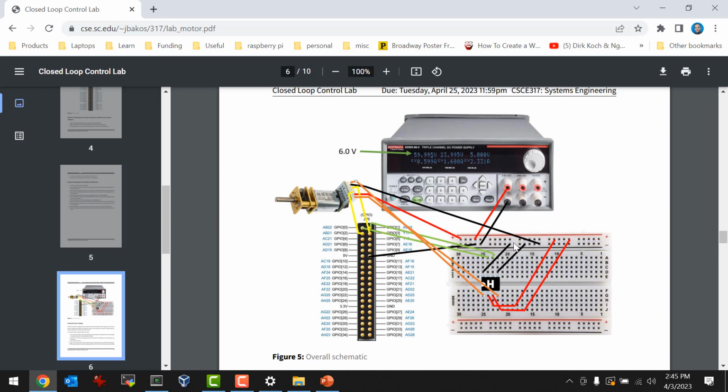Now, this picture is a little bit misleading because the breadboards that we have in the lab only have 1 power supply rail, and it's at the bottom, down here. This is just a generic picture I got from the internet, so try not to be confused by that. I don't know why we only have one power supply rail on the ones in the lab, but you can just connect the plus to the plus side and the ground to the minus side there. Then you connect the ground back to the ground connector on the FPGA, so you'll get a common ground.